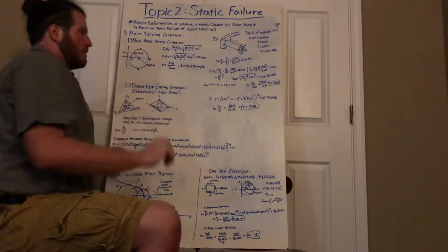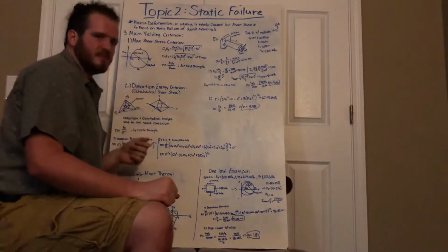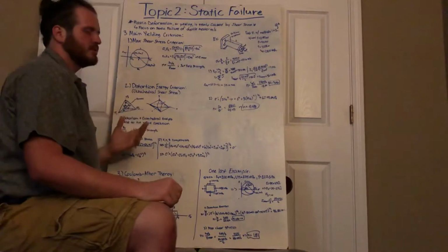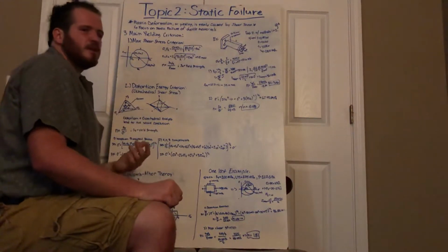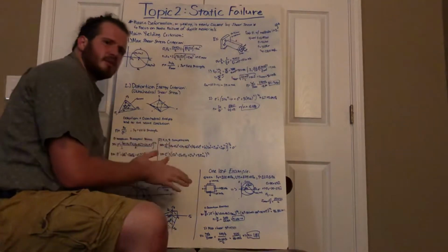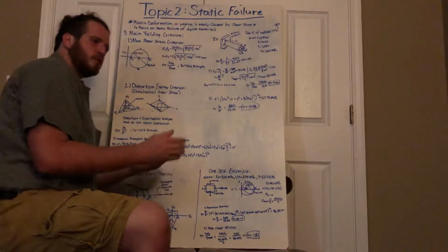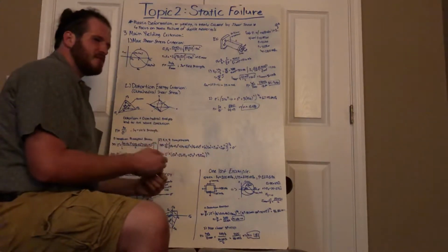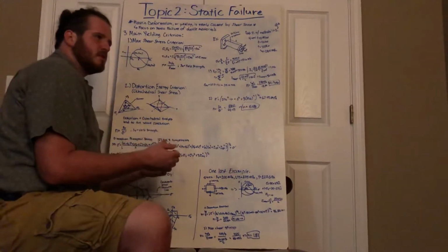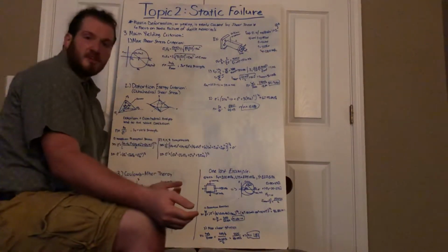Now, what is this all leading us to? Well, it's leading us to developing factors of safety. Factors of safety are important in engineering because you want to be able to build something without always pushing it to the edge, pushing it to the limit of materials properties, materials capabilities. So we always try to factor in a factor of safety that isn't cumbersome to what you're planning, but also allows for a safe margin.